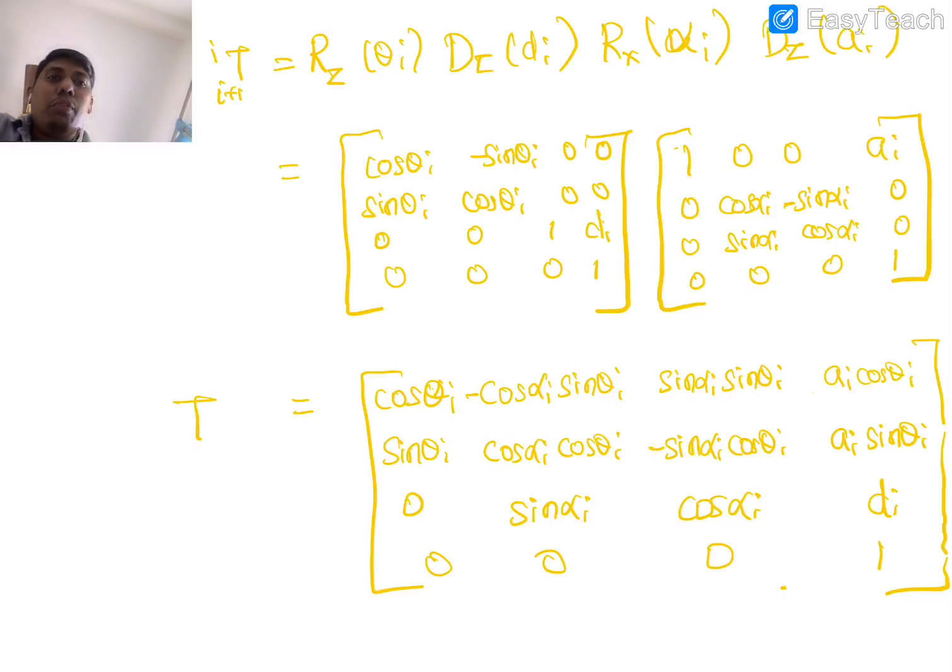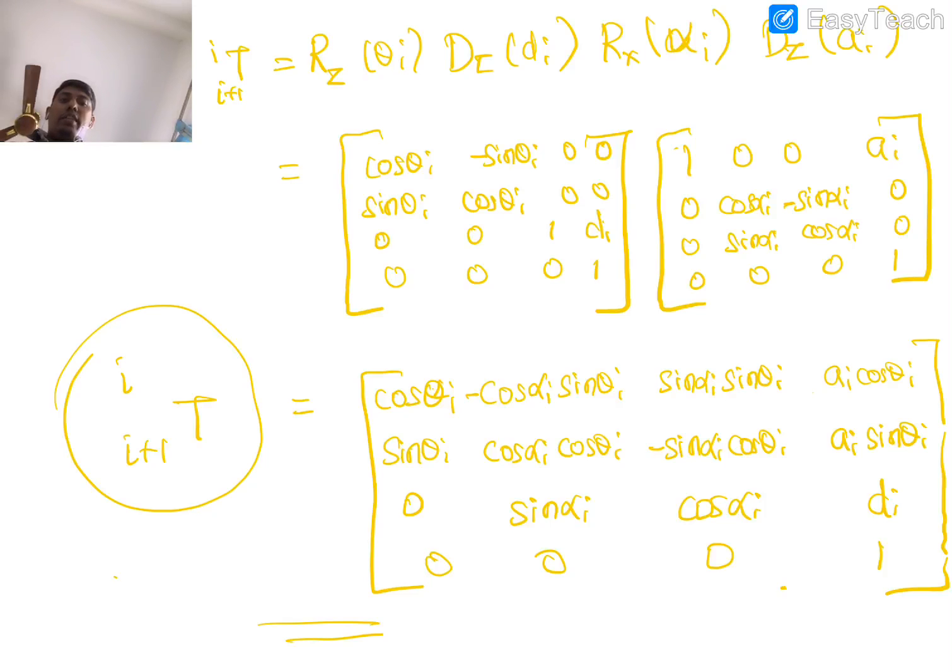So now this is the A matrix based on what you call the standard form. Most of the textbooks would write it like this. In the sense, they start with the joint frame 1, not 0. If somebody starts with 0, then confusion will come, but if you start with joint axis 1, then this is the form, and this is what most textbooks write. For example, in Professor S.K. Saha's book, this would be written in this way. So this is the standard form.